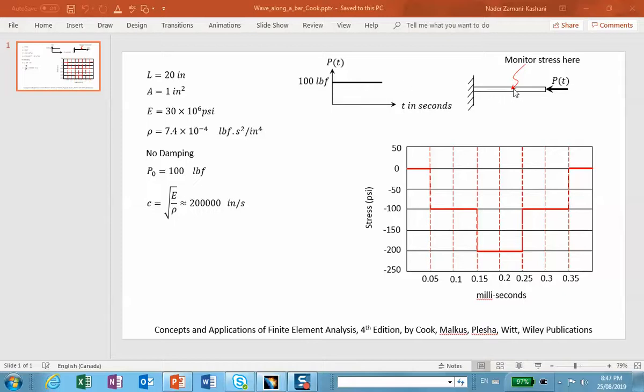In other words, as soon as the load is applied, a pressure wave will travel down the path, and eventually it reaches the wall. It hits the wall, and then it gets reflected, maintaining its magnitude, and of course also compressive in nature. For example, if you look at this point in the middle, and this is the location that we're going to be modifying, based on that speed that I have, there is nothing happening.